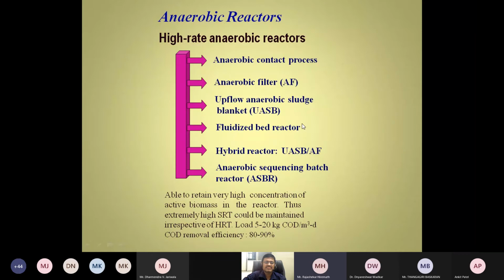The microorganism and nutrient load, your aeration load will be very high in that case. I told you initially that if organic matter is more, the bacteria will start degrading it and require more oxygen. I am talking about 300 to 400 milligram per liter, but if you have 40,000 or 50,000 milligram per liter of BOD, that is so much organic load.